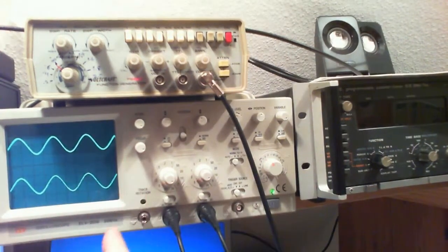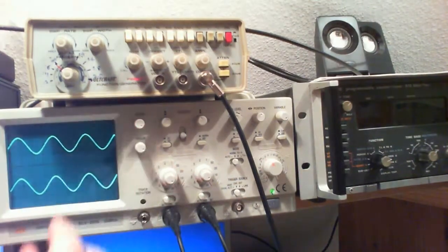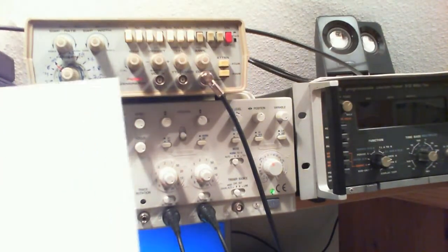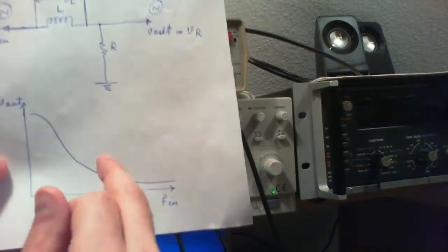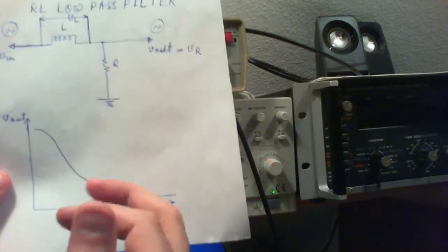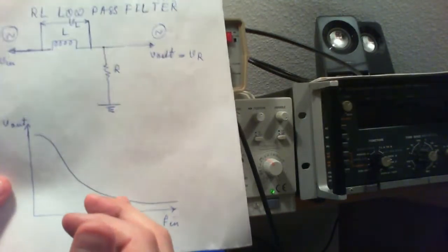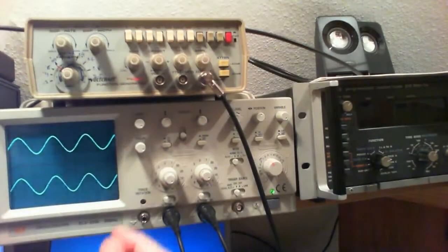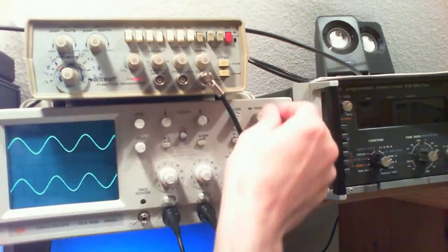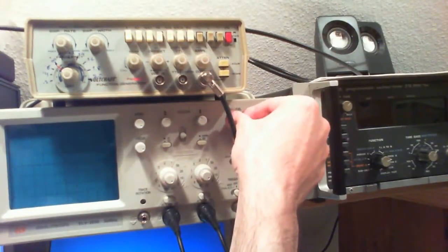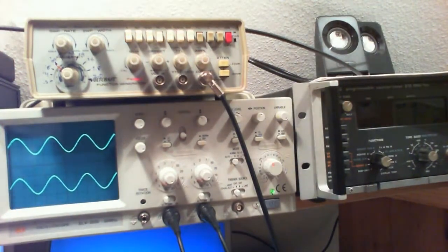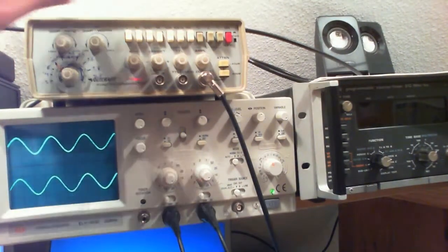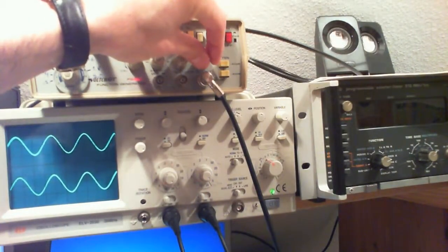Okay, so now you want to actually increase. So you said that over here, what happens is that you have to increase your signal so that the voltage drops, and the voltage drops over here, I think somewhere around 100 kilohertz or something like that. So let's see where it drops. But before I do that, I want to basically make the amplitude of this signal 10 volts peak to peak. So I make this 10 volts peak to peak here.